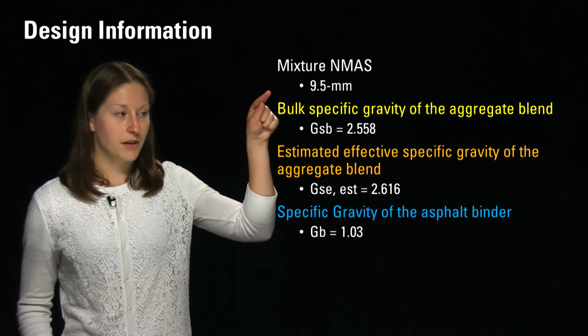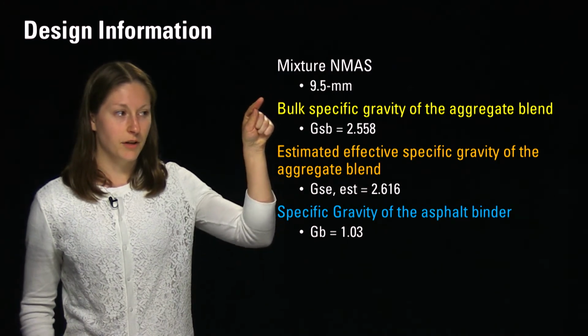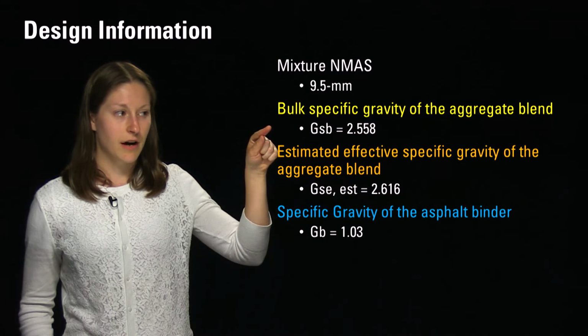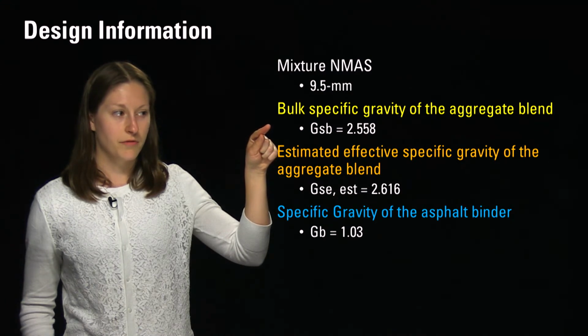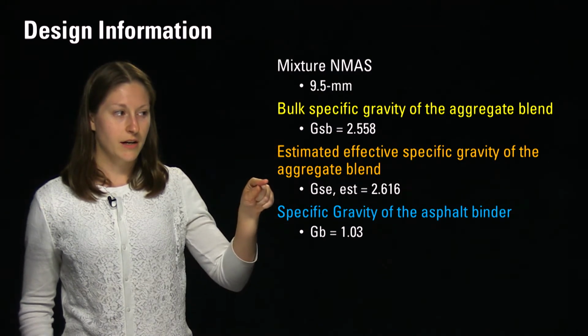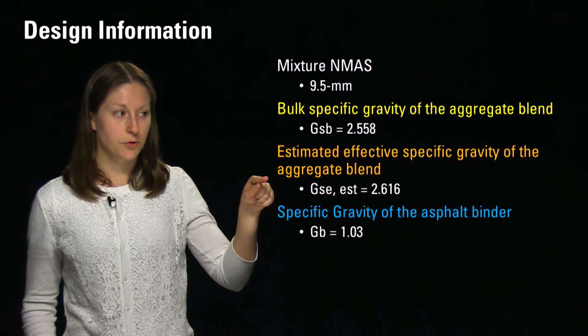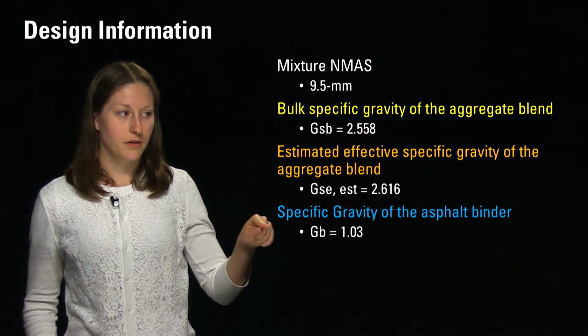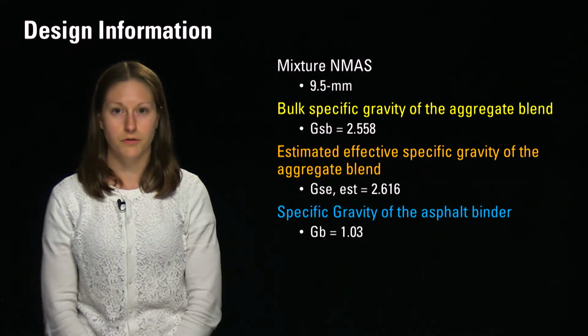Our mixture nominal maximum aggregate size is 9.5 millimeters. Our bulk specific gravity of our aggregate blend is 2.558. Our estimated effective specific gravity is 2.616, and our binder specific gravity is 1.03.